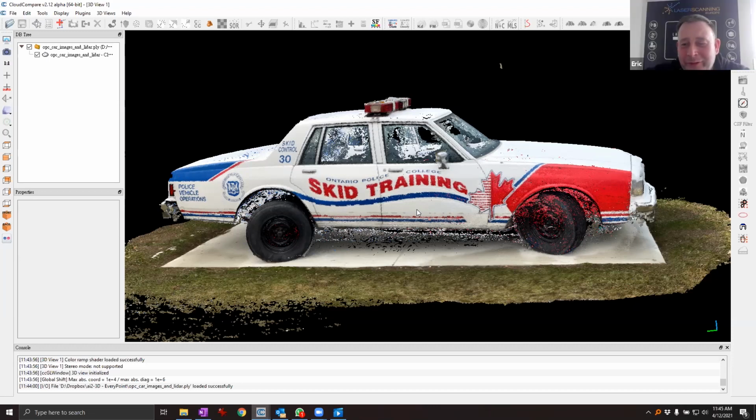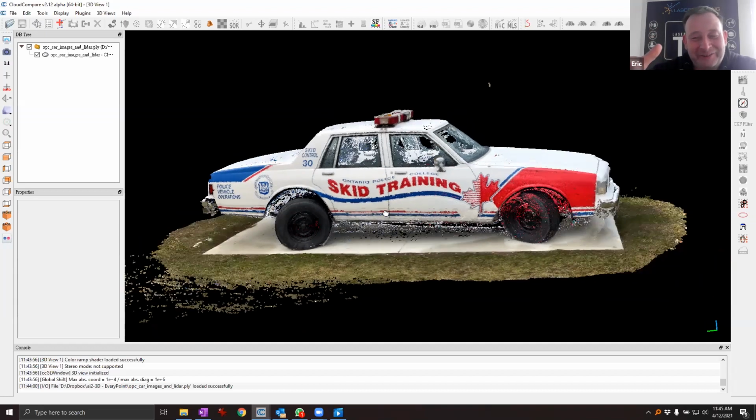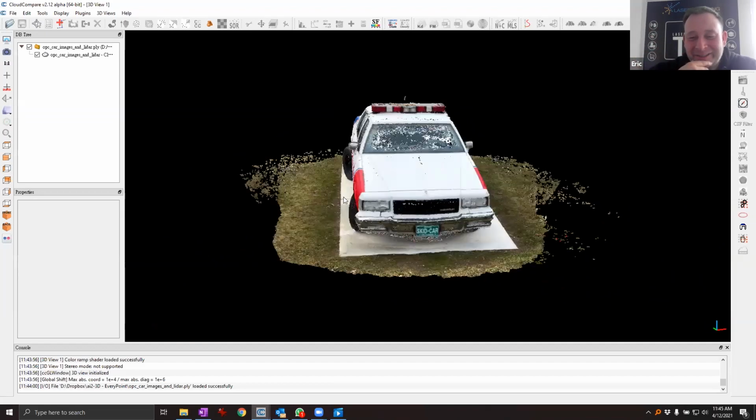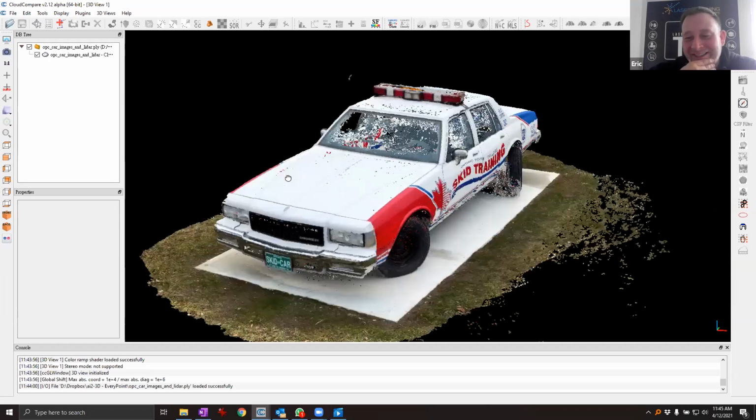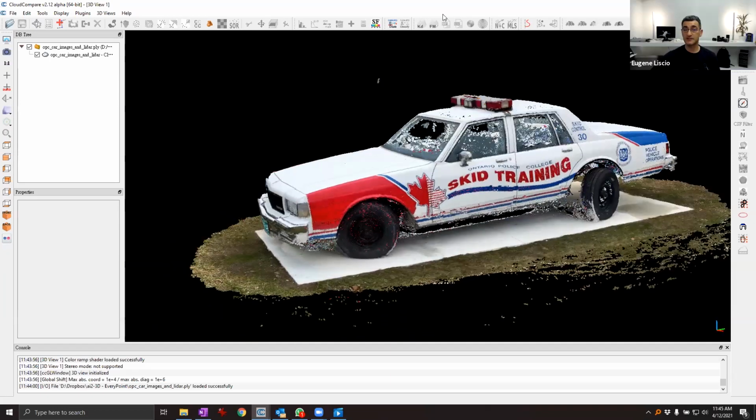Maybe also if you can put some scale factors in, so that they can scale it. I think it's only a calculation. Yes. So maybe you put three or four little targets or control points down, and then you measure this with a distance measurement. Maybe you have only two markers in the field, and you know the exact position between the two markers, and then you scale it exactly. Yeah, that's exactly right.